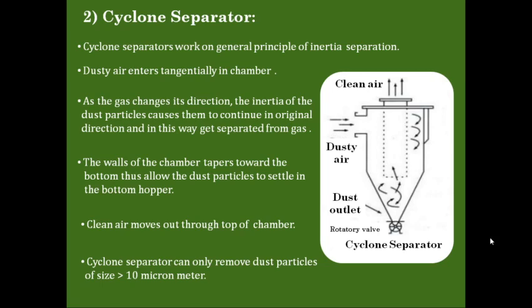So we'll have to look for another better equipment which can remove particles of size less than 10 micrometer also. Cyclone separators can be very easily seen in different kinds of industries because these equipments occupy very little space as they are vertically elongated. The polluted air is allowed to enter with a good velocity, so in less time we can purify large volumes of gases.